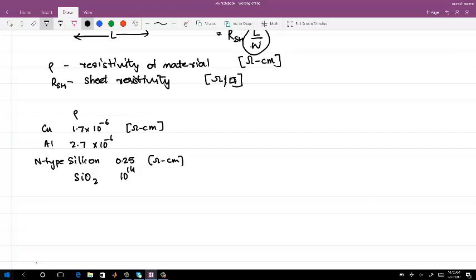And if you do not do anything, plus minus 20 to 30% of resistor variation can change your loop gain, margin, noise performance, everything. It's not only about the noise which is being contributed by the resistor, it is changing the whole loop dynamics and bandwidth, which changes the noise contribution of other blocks in the system.